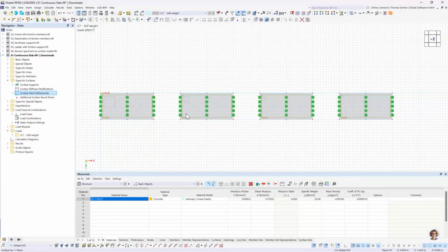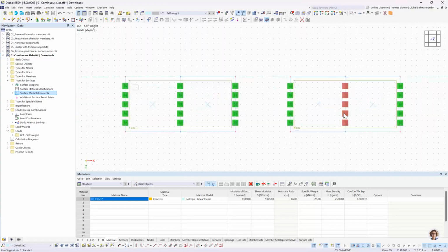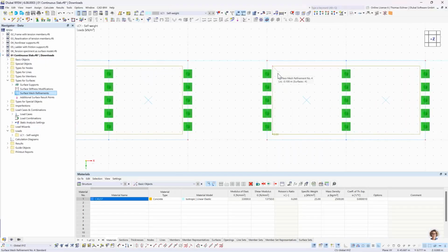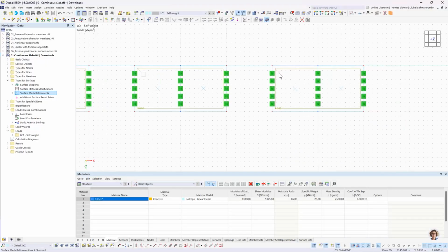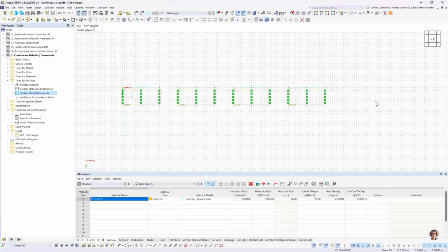And those rectangles, we can see it also for every surface, maybe like this, show us what the desired size of these finite elements will be. So here, our quite coarse 2 meters length, and here, well, we would have to zoom in to even see how big this element is. So that's really fine. Okay, so now we have the system created.